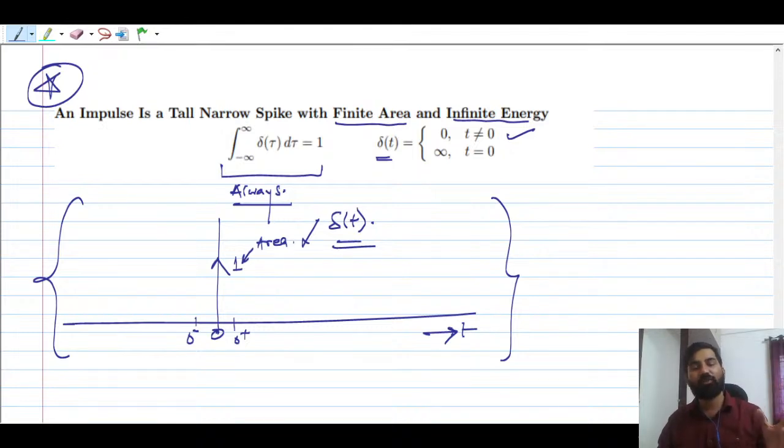So the sinc function is one of the very important concepts that is going to be very useful in signals and systems when we talk about the Fourier transform of a rectangular function or a triangular function. It will also be useful in digital communication because most streams of bits are going to be encoded using some line coding. So there will be a pulse we are going to use, and the Fourier transform of the pulse is going to be that sinc function.